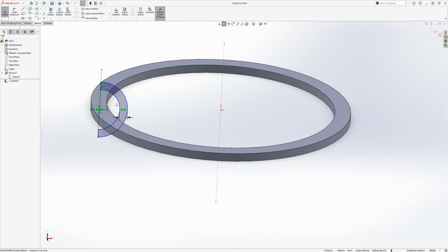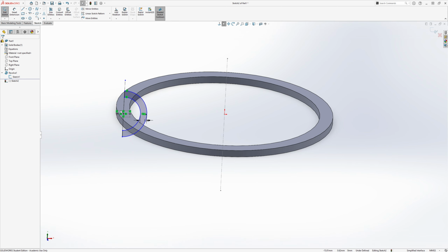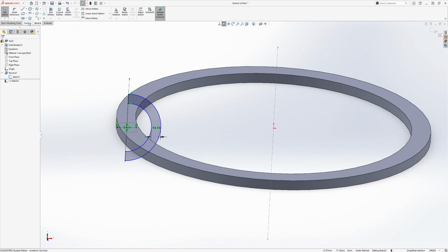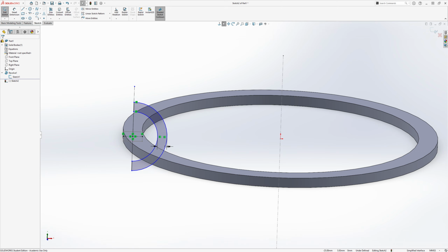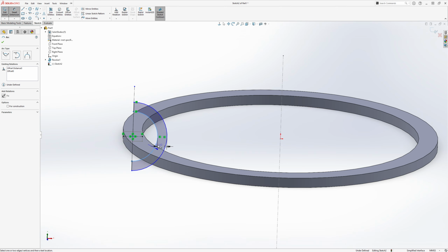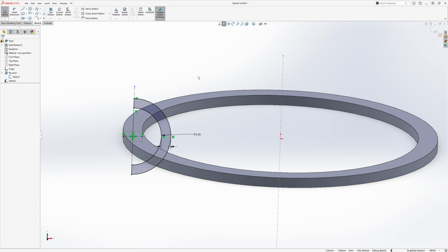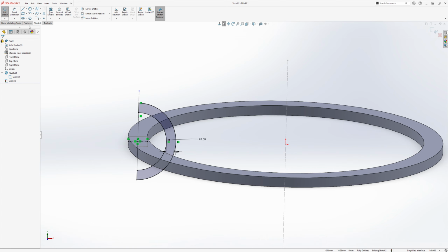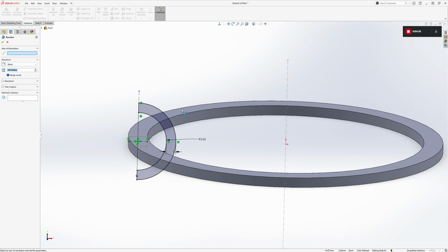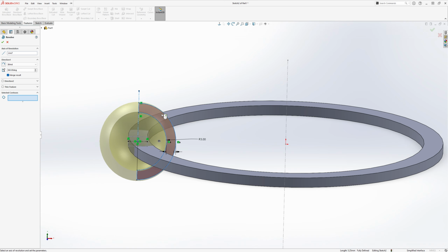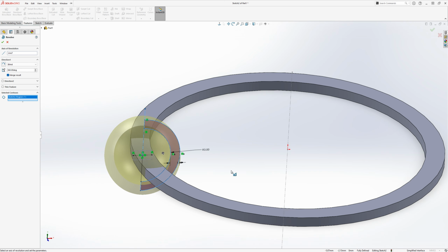And it will have to do a cut on the inside in order to clear that out. But you won't be able to see it. But first we need to fully define this. So the inside radius is going to be R3. And from here, we're going to revolve, choosing this as the axis of revolution, and then this as the contour. See, it is not hollow.